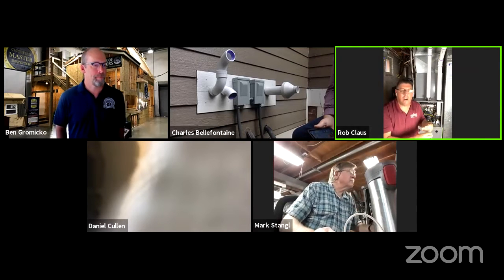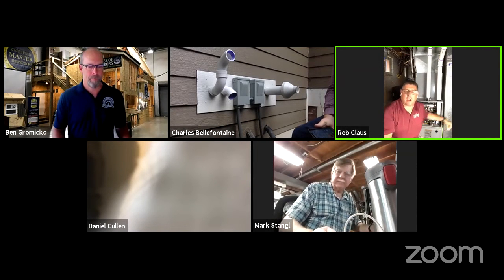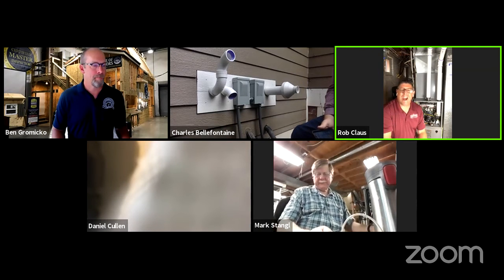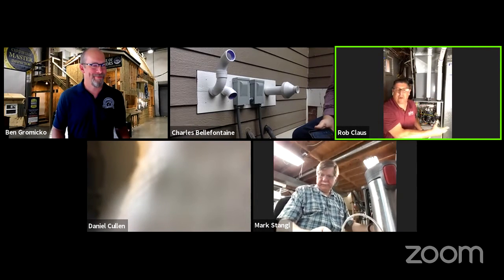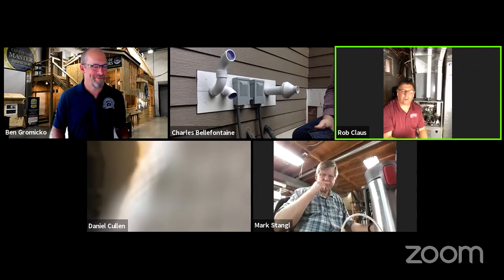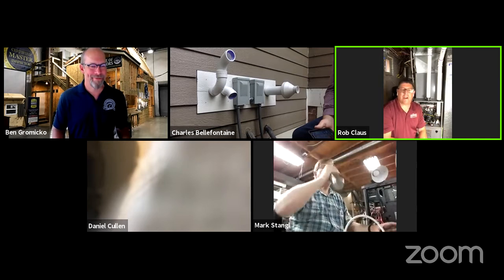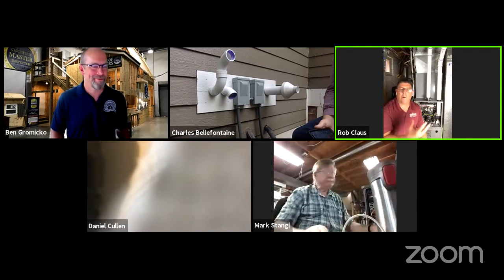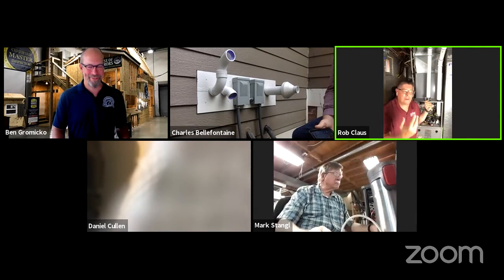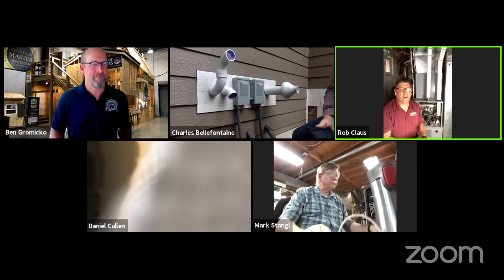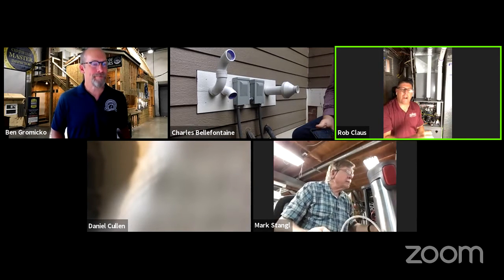Who's right? Who's wrong? Well, if I take a temperature check across the system, take a simple picture of the thermometer and say, this one's there and this one's there, and do the math. I went to public school. I can subtract a little bit. And if I come up with that math being higher, it's like going to Vegas. If it says between 40 and 70 delta works, 71 fails. Just as simple as that. You don't get 22 and they go, well, you almost won. And so that's what I do.